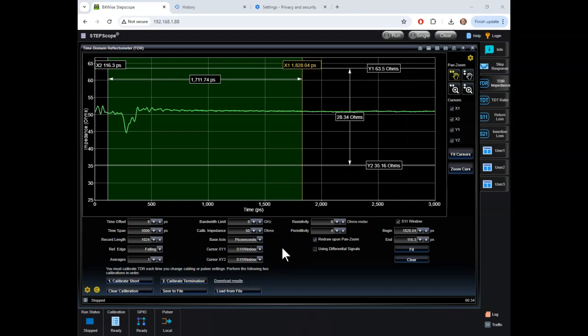We hope this measurement example has been helpful. Using windowing is particularly beneficial when you're working with large discontinuities in your test structures. For example, sometimes it's inevitable when adapting to BNC connectors or 75 ohm BNC connectors when making those types of measurements, and being able to window them out is an effective way to make a measurement of your real system.